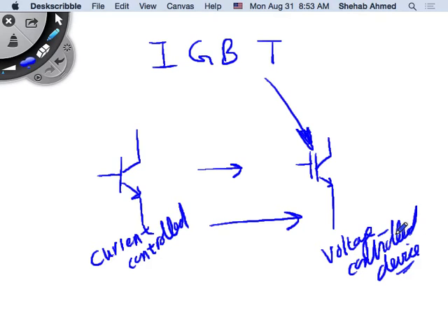The beauty is this. MOSFETs have these parasitic diodes. They are very difficult to construct for very high voltages and very high currents, especially because of this poor diode, right? So BJTs are beautiful. BJTs are an excellent kind of device. You can push it to very, very high voltages. You can push it to very, very high currents.